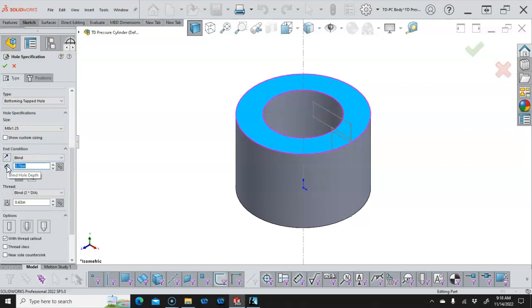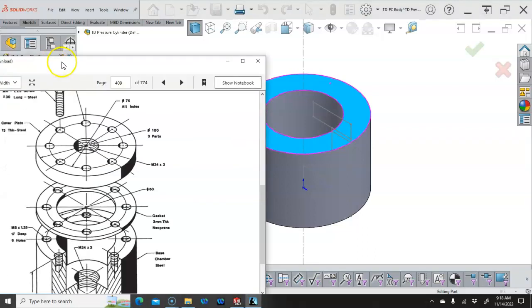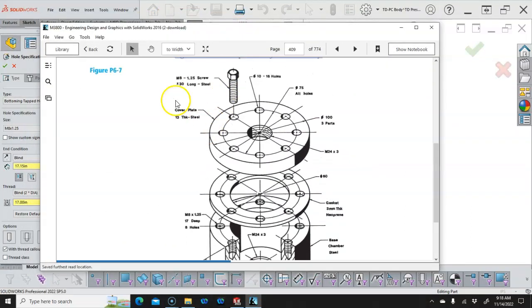And you want to make sure that when you put this in, we're going to do 17 millimeters. And what ends up happening a lot of times on the manufacturing side is if we do this math, we're 30 millimeters long, which will be pretty close. It's somewhere between 29 and 30 on the length of the screw. It's going through 13 and 3, which is the 16, and another 17 would be 31. So a millimeter of clearance, not real great.